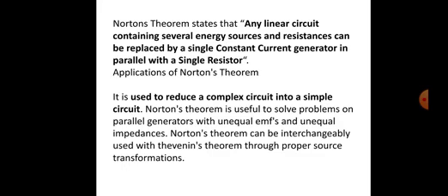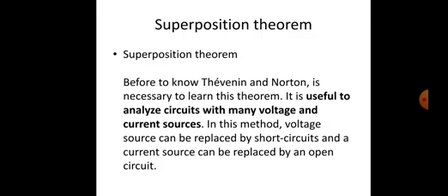Step 5: Draw the Norton equivalent circuit with the Norton current source in parallel with the Norton resistance. The load resistance reattaches between the two open points of the equivalent circuit. Analyze the voltage and current for the load following the rules for parallel circuits. Next we will see the superposition theorem.